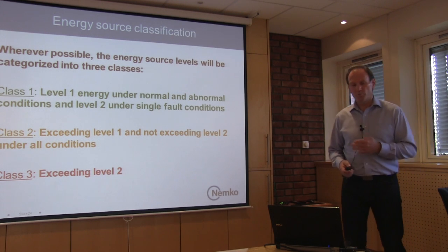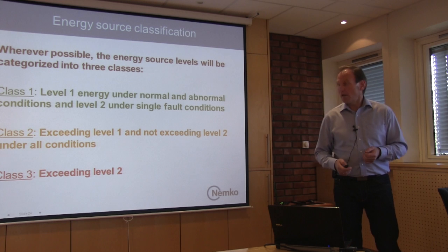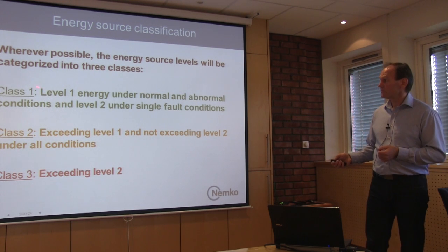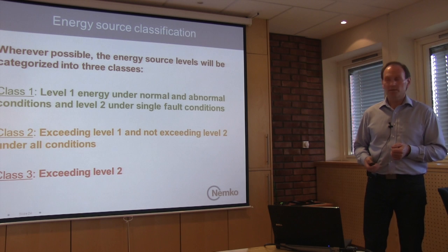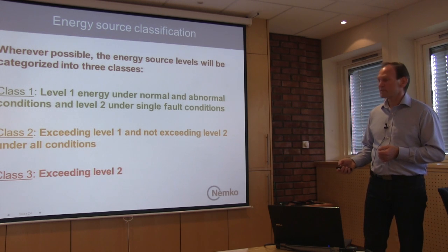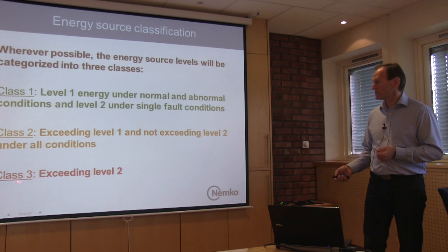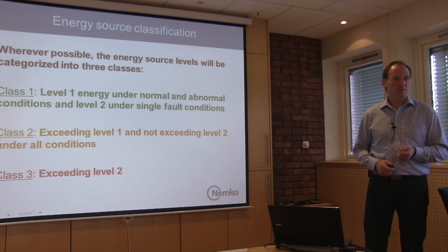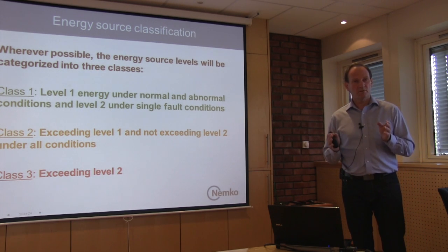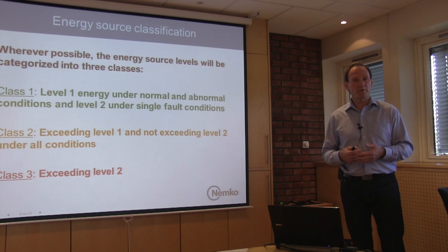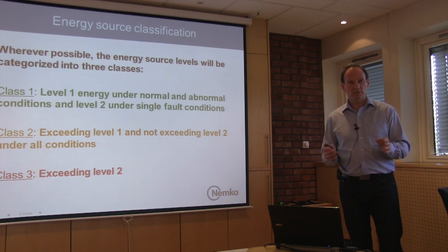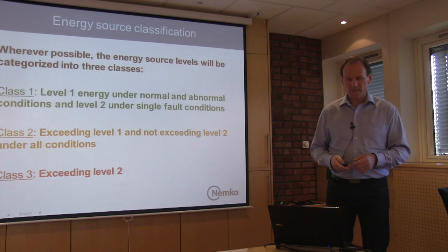Compared to the present standard, I would say class 1 is similar to SELV today. Class 2 is similar to TNV. And then we have hazardous voltage as class 3. It's not directly comparable, but it's similar.